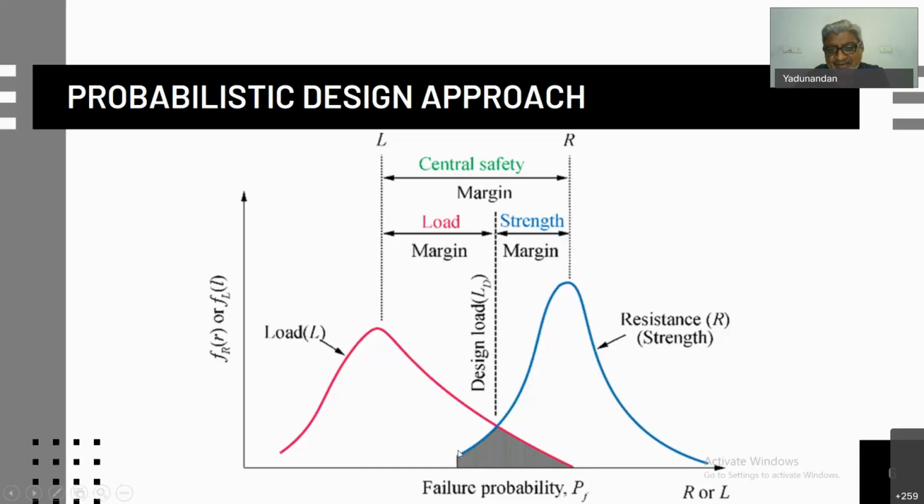So if the normal distribution curve for the load is this, we have to set a normal distribution curve for the resistance, the blue line graph, which is quite a bit higher than the load values, and its variation is seen like this. And this value of the resistance is scaled down considering the reliability of the material, how reliable it is, how acceptable it is.